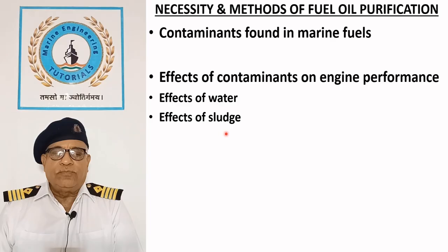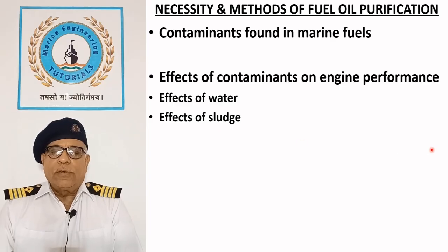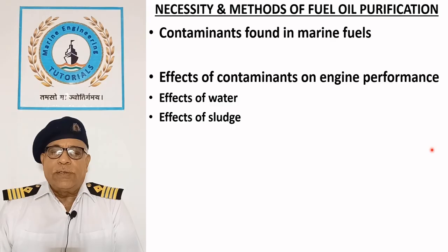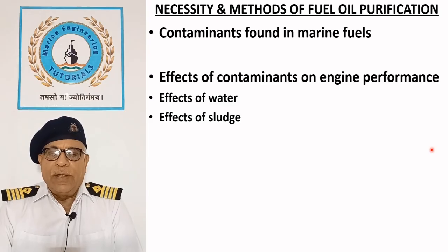Effects of sludge. Sludge consisting of asphaltene and sediments may clog the fuel filters and injectors. They cause abrasive wear on fuel pumps, injectors, cylinder liner, and piston rings. They are also responsible for incomplete combustion, resulting in deposits on piston crown and turbochargers, which increases maintenance frequency and unplanned downtime.